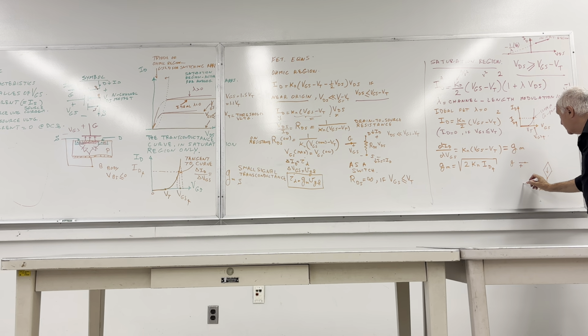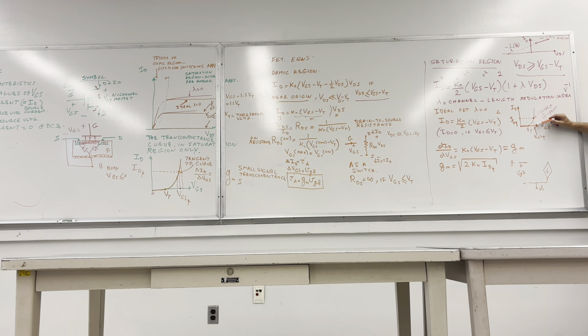This voltage will be marked lowercase VGS. That's the tiny increment from that point to the left, to the right. It's this VGS operating to the left and right of the nominal VGS, which is the Q. And then here you would have the drain D, and this current would be ID equal to GM multiplied by VGS, the small change in the VGS. That's it. It can't be any simpler than that.